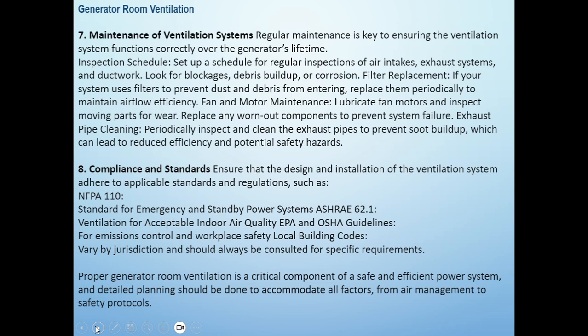The filter replacement. If your system uses filters to prevent dust and debris from entering, replace them periodically to maintain airflow efficiency. The fan and motor maintenance. Lubricate fan motors and inspect moving parts for wear. Replace any worn out components to prevent system failures. The exhaust pipe cleaning. Periodically inspect and clean the exhaust pipe to prevent soot buildup, which can lead to reduced efficiency and potential safety hazards.